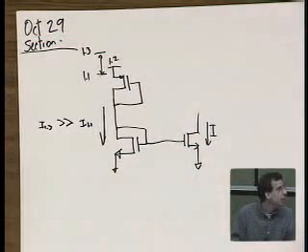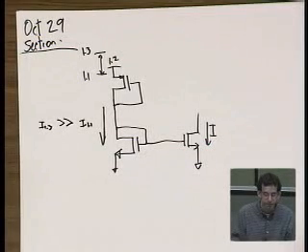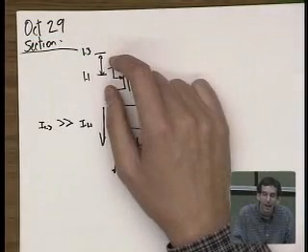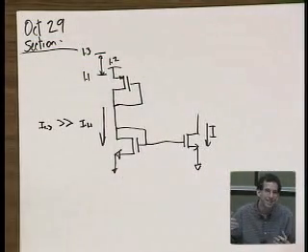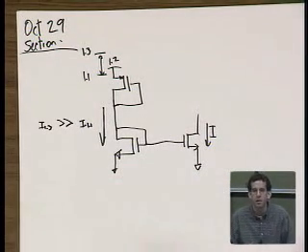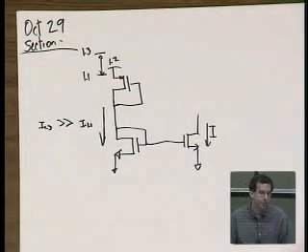So if you make a bias circuit that doesn't have good power supply rejection, then your bias current is going to vary all over the map as you vary your supply, and as a result, that'll be another thing that's changing in your design, and that'll make it hard to consistently meet all your specifications all the time.